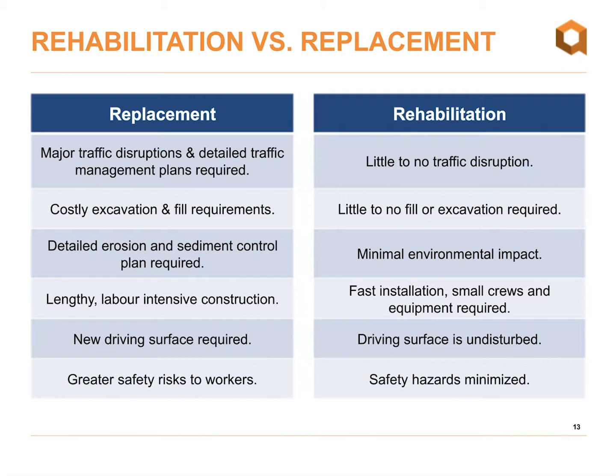Secondly, we have little to no fill or excavation requirements, so we don't need to dig up the existing structure, particularly for potentially buried culverts that may be under large amounts of fill. We've seen structures buried as deep as 15 to 30 meters. So in order to prevent excavation requirements for those systems, rehabilitation can be a great cost saver. We're saving on moving that material out and then also bringing in replacement, potentially well-graded granular backfill.